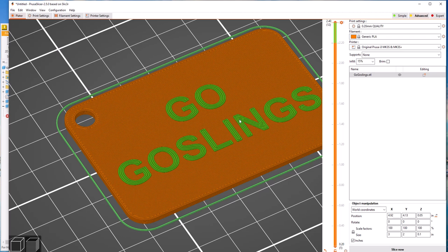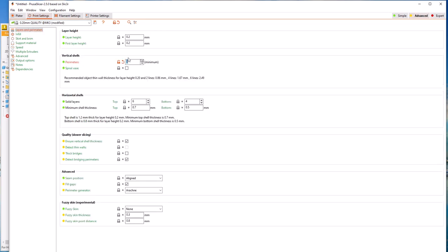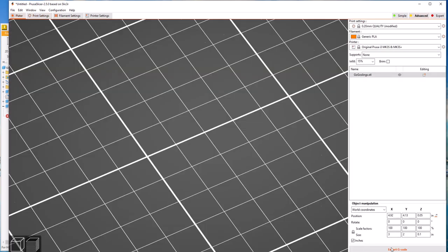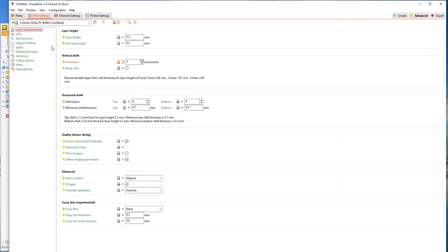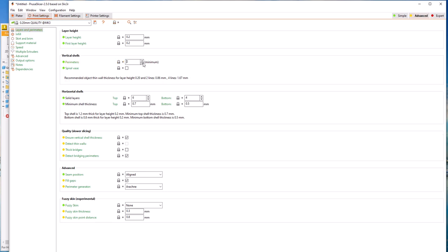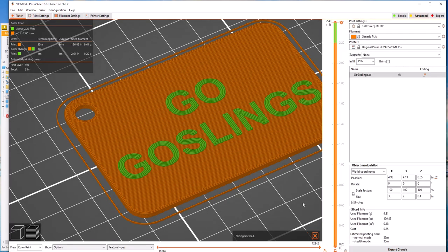We're doing a 2 wall thickness on the part because it doesn't need to be real strong. If we come in here and change it from a 2 to a 3 and re-slice it, it's going to make it 3 everywhere, but now we don't necessarily have the infill on the end. It makes this little goofy pattern, I guess, so it's whatever you prefer for a look, but it had to fill that end in somehow, whether it is wall or infill on that process.